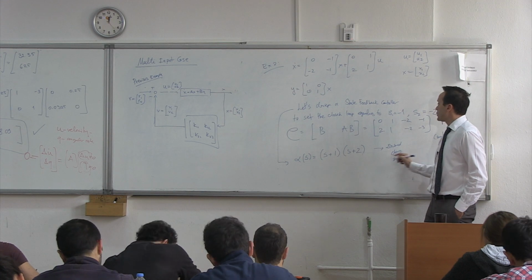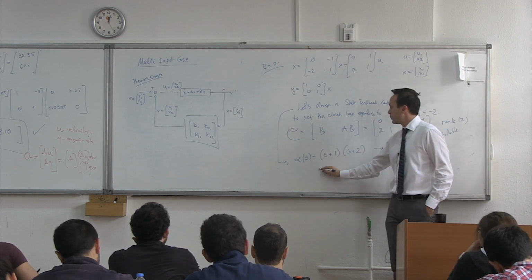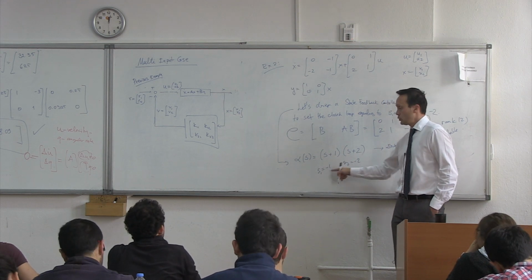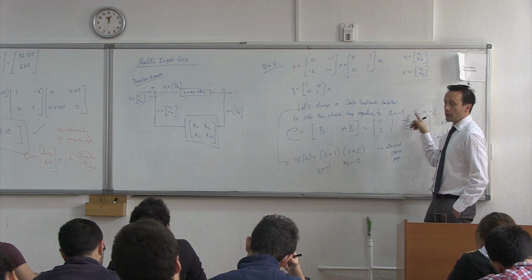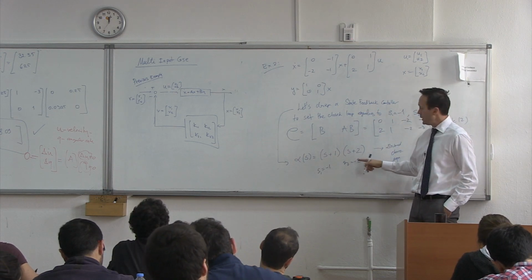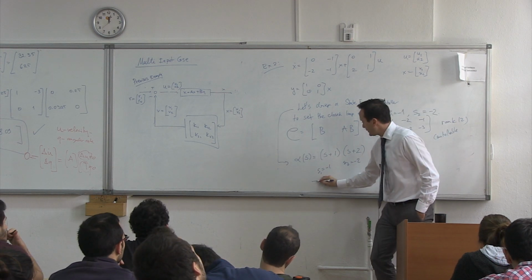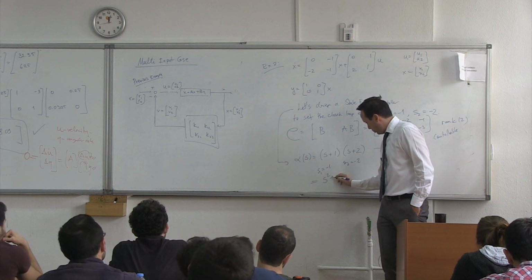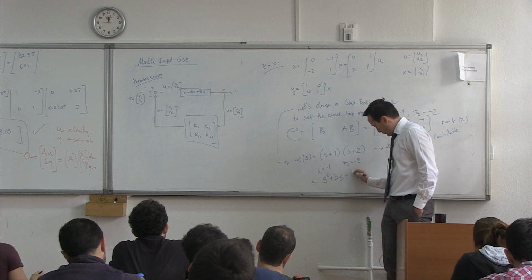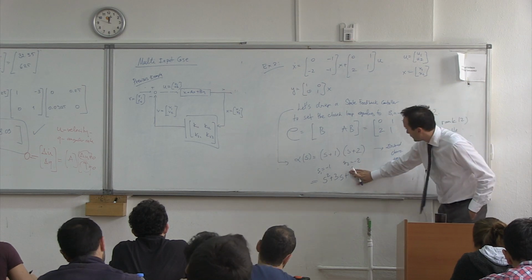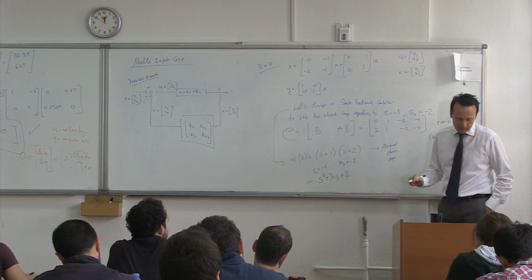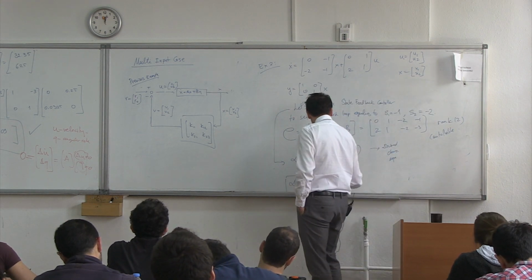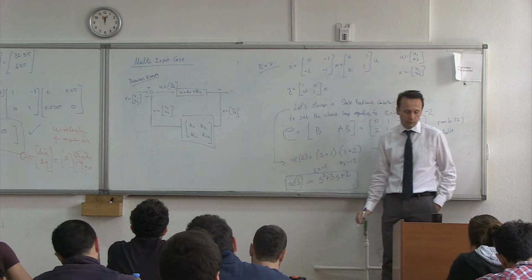Characteristic equation. So why is it like that? Here S1 is equal to -1 and S2 is equal to -2. So this is the desired characteristic equation of the closed loop. It's -1 and -2, and it should look like this. So if you write this as an equation, you will get S squared plus 3S plus 1. Or plus 2, I'm sorry. Right? Plus 2. So that's your desired characteristic equation. So you want your closed loop system to look like this.